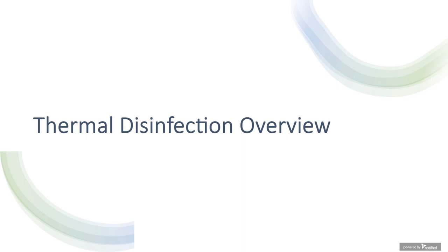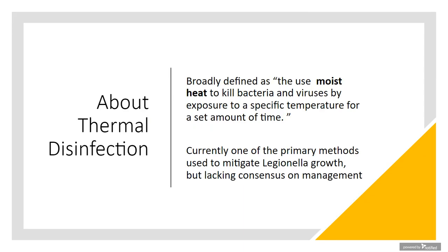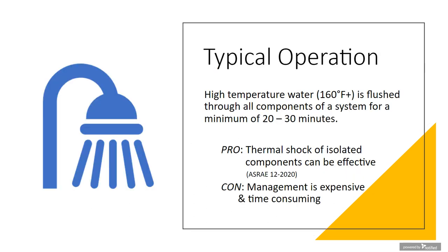So, thermal disinfection overview. In a broadly defined explanation here, it is the use of moist heat to kill bacteria and viruses by exposure to a specific temperature for a set amount of time. Thermal disinfection is currently one of the primary methods used to mitigate Legionella growth, but definitely lacking consensus on how to manage that process.